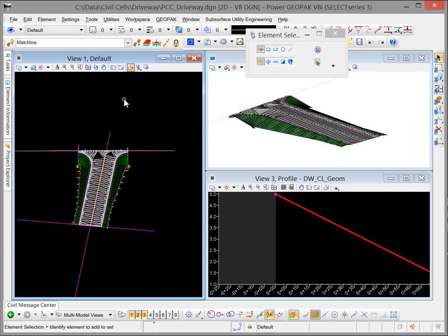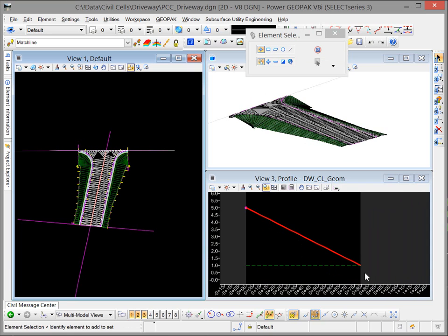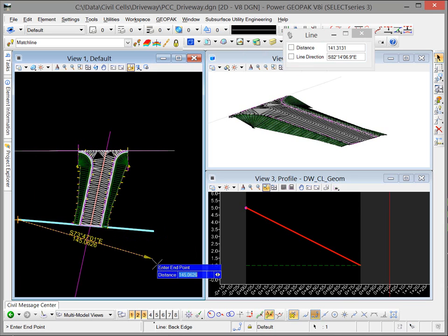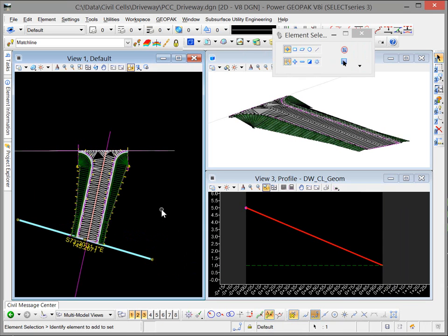And so this really shows a lot of techniques. It shows how to create a profile along the edge, and where it ties to the main line edge of pavement, and it also ties to the existing terrain model. And you saw there were some very specific steps that you had to take to construct these profiles. We also showed how we complexed the radius with the tangent and then placed a linear template along there, and how we've incorporated the ability to use MicroStation trim elements, so that our back driveway edge does not have to parallel our main line edge.